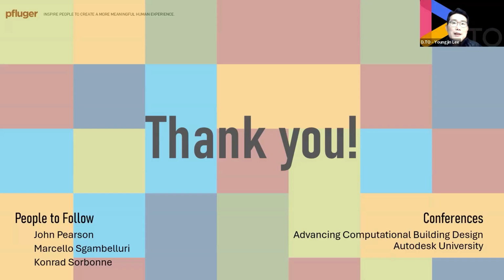Gotcha, gotcha. This is my last technical question, Jacqueline. When I create a bunch of Dynamo scripts and share them via Dynamo Player, I get a lot of complaints: none of your scripts are working for me. I think that happened because of the type parameters, for instance. Some people put a name, then a dash, and then another text, instead of the underbar.